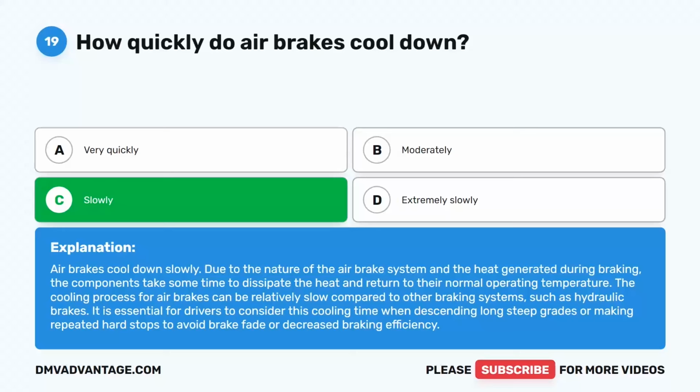Due to the nature of the air brake system and the heat generated during braking, the components take some time to dissipate the heat and return to their normal operating temperature. The cooling process for air brakes can be relatively slow compared to other braking systems, such as hydraulic brakes. It is essential for drivers to consider this cooling time when descending long, steep grades or making repeated hard stops to avoid brake fade or decreased braking efficiency.